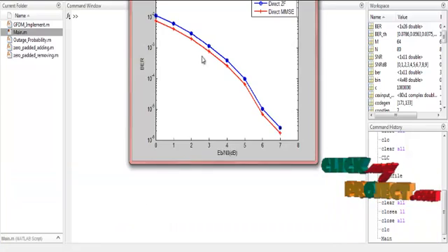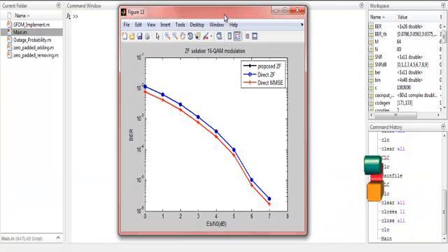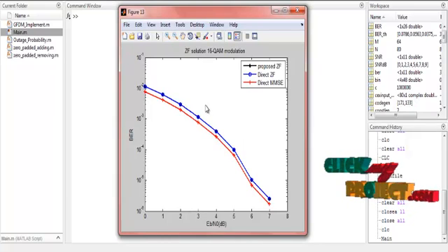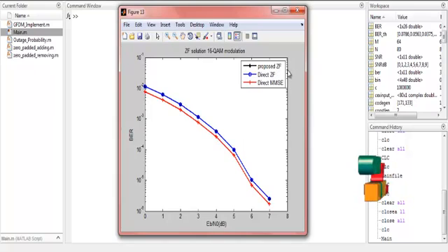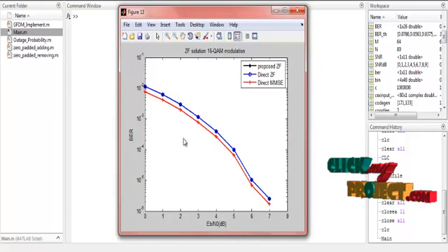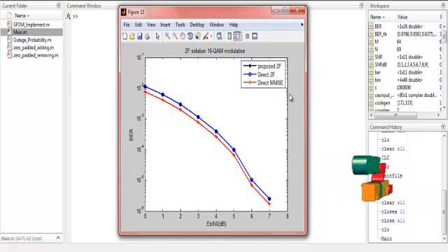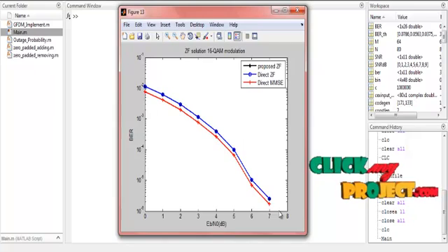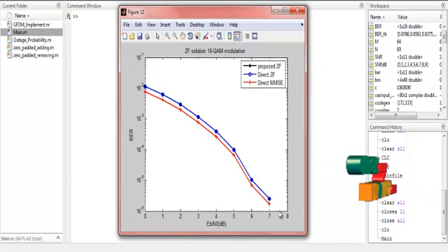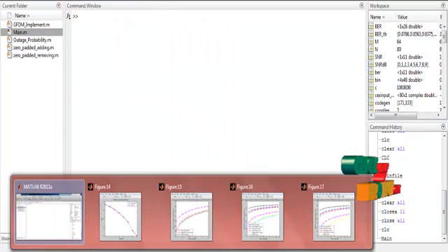In the next figure, ZF equalization is for 64 QAM modulation. That is 64 QAM modulation, and this is 16 QAM modulation. This is the ZF solution. The proposed ZF is shown in black and blue. The direct ZF and proposed are more or less the same, and the direct MMSE is the minimum mean square error. For Eb/N0 in dB, the BER should be reduced. The previous figure is 64 QAM modulation, and this is 16 QAM modulation of the process. These are the different types of process.